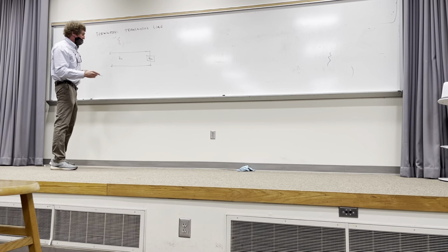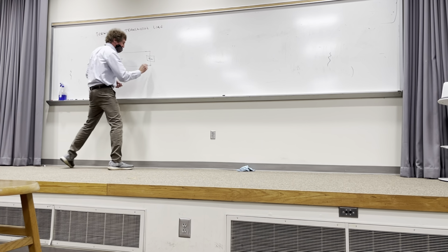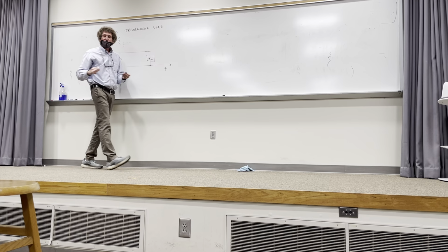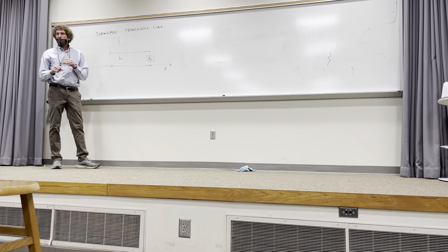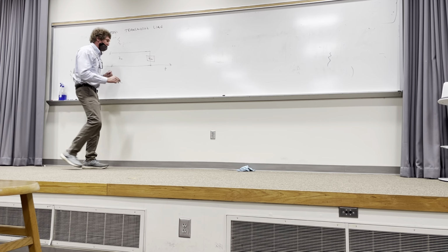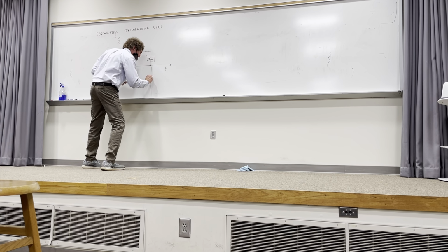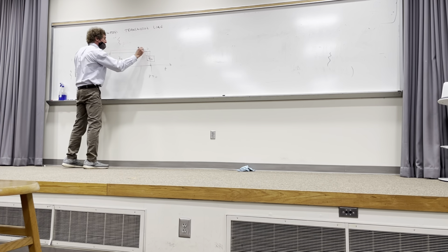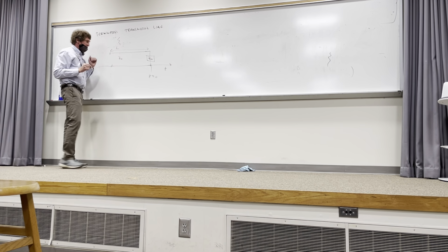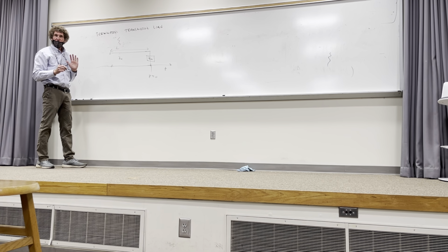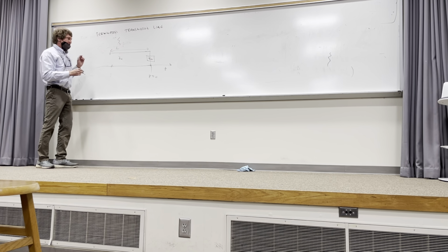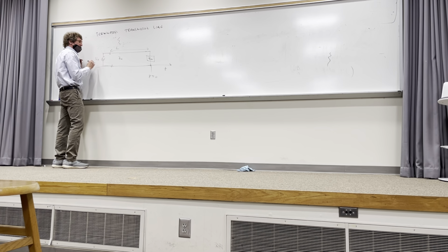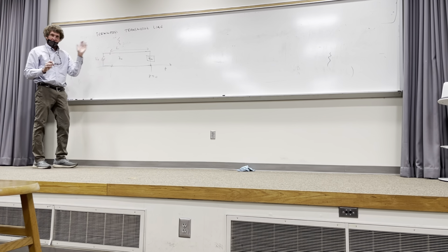All right, when you have something like this, you need a reference, so we're going to use this as the z-axis right here. And this is a trick, and it saves some math. We always place the load at z equals 0, so call this z equals 0. Now the transmission line has a given length, L. And this is the input to it, but for now, just go with me on this one. We can say that there's a voltage source here that's going to have some V naught, and it's going to cause waves to go down and back. You all follow me?